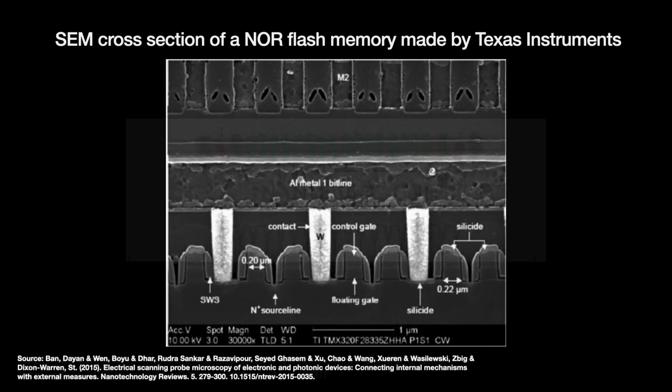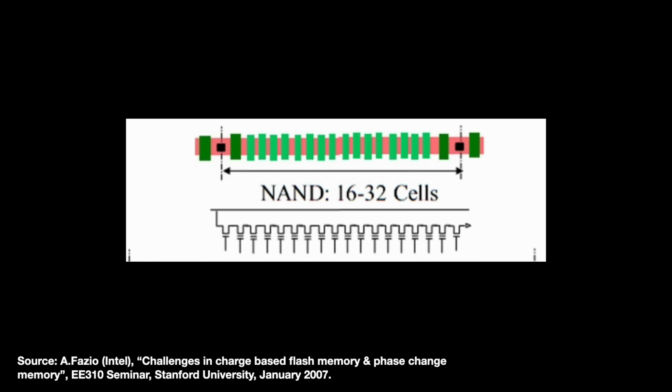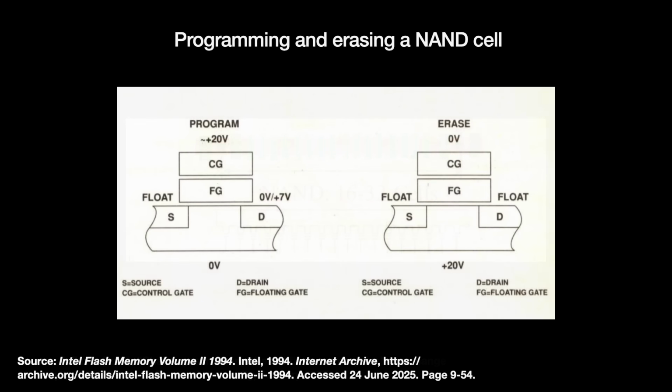For NAND, it's different. Their cells being so densely packed together made hot electron injection impractical from the get-go. So Toshiba used the Fowler-Nordheim quantum tunneling method normally used for erasing the cell, and that turned out to be more scalable over the years. The NAND industry also introduced a series of clever and critical innovations to grow storage capacity. One of SanDisk's early innovations, filed all the way back in 1988, involved having a NAND cell store 2 bits rather than just 1, the multi-level cell.